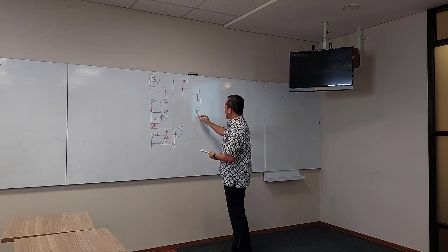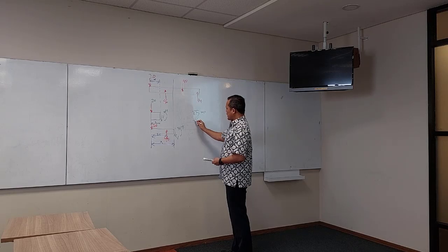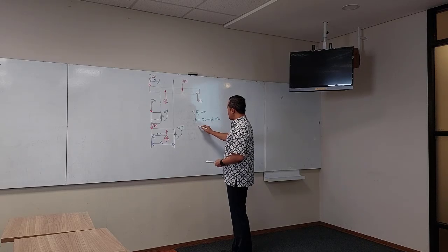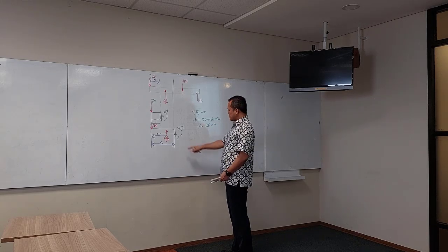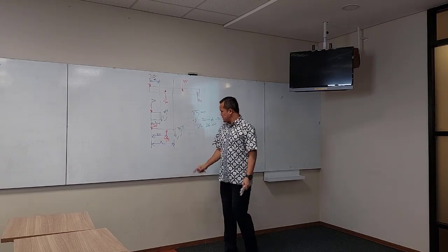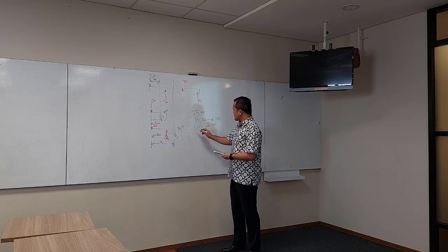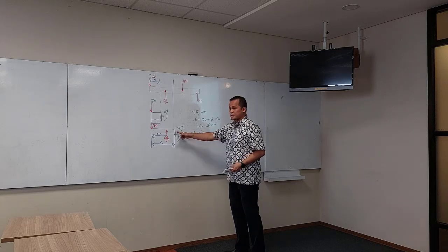Sigma Fy equal to 0 will give you V negative, minus 20 plus 46 equal to 0. Therefore V is equal to 26 kilonewton. Okay. Look, it is positive now. The V becomes positive. Okay, now M. Sigma M equal to 0 at this point.